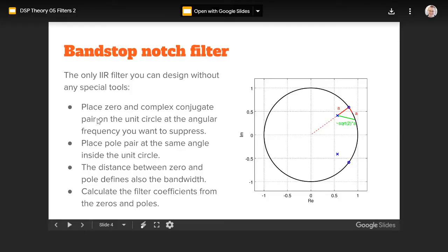Although when we have this chopper, the DC converting kind of things, then this can be anything and varying and ugly. But in the ideal case, you have a really nicely behaving linear power supply, and then you still have a little bit of humming because you have a 24-bit A to D converter. 24 bits. You get down to microvolt levels. It's about 1 microvolt resolution.